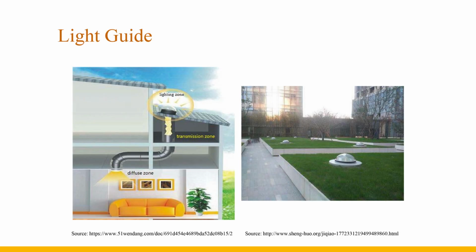The light pipe lighting system is a new type of roof lighting technology, which uses light pipes to conduct natural light from the roof to the interior. Optical components are used in the collection, transmission, and diffusion of natural light, which improves the utilization efficiency of natural light and the possibility of utilization inside the building. It is suitable for basements, spaces with no windows, large depths, or spaces that are not suitable for opening windows.